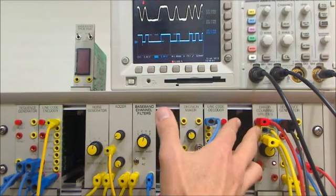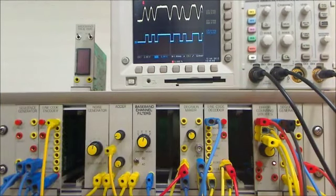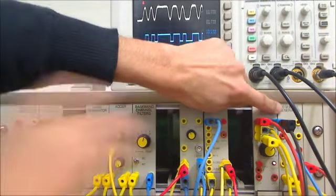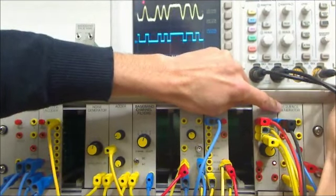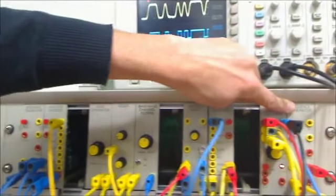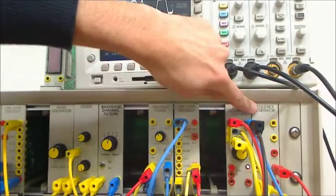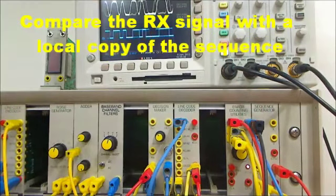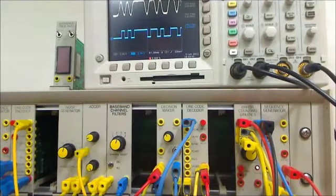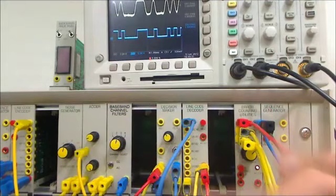So we'll use the error counting utilities module, which comprises an exclusive OR function which acts as a comparator. What we do is take the signal from the decoder and compare that with a local sequence from a local sequence generator. We have a second sequence generator module, which has the same sequence in it as our original sequence generator. We're going to take measurements of the number of errors in the channel due to the noise.